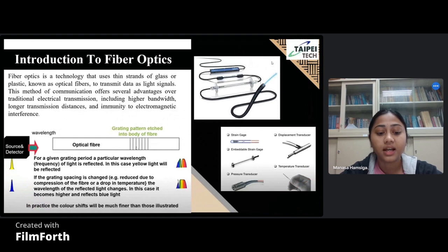Introduction to optical fibers. A fiber optic sensor is a sensor that uses optical fiber as a sensing element or as a means of relaying signals from remote sensors to electronics that process the signals. Fibers have many uses in remote sensing. Depending on the application, fibers may be used because of their smaller size and because no electrical power is needed at the remote location. By sensing the time delay as the light passes through the fiber, each sensor can be multiplexed along the length of the fiber.